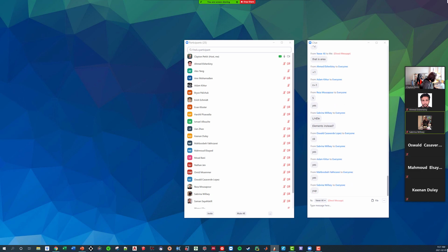Yes, perfect, perfect. So we have our beam. Now we know that we are doing 4 elements, so therefore we have 5 nodes. So if I were to go, we got node number 1, 2, 3, 4, 5. 5 nodes. Now each one of these nodes has 1 degree of freedom, right? We already talked about that.